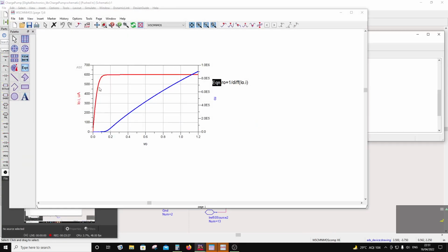What I'm plotting here is the current mirror response. So 0.1 is where it has to be, and the output transistors have to be in the saturation region. So that's basically twice the overdrive drop across the devices. And the blue one is the output resistance I've plotted, and that output resistance is of the order of 100 kilohms on the way up to almost 1 megaohm.